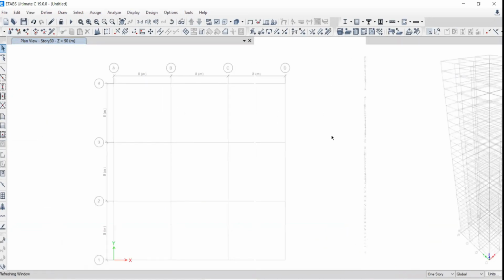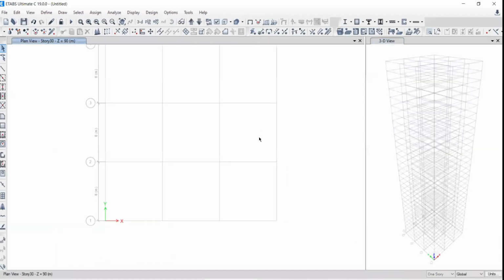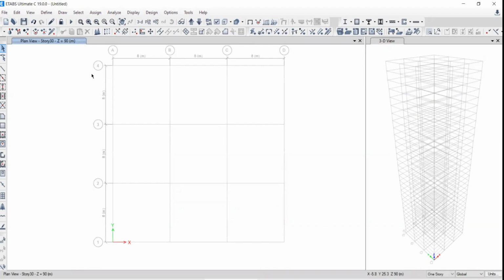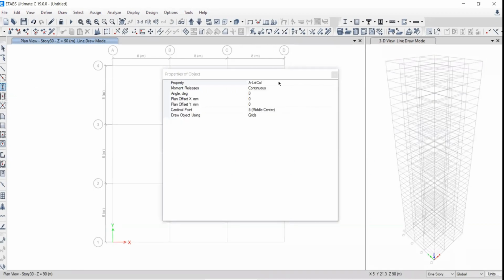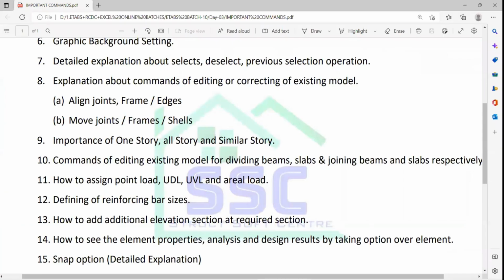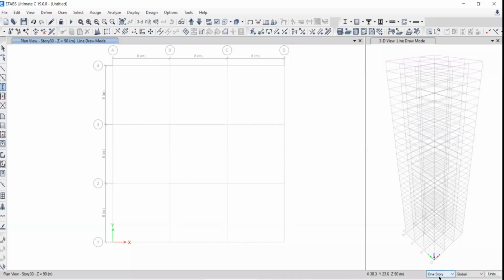How will this help you for the modeling? Now, suppose I have to draw the column at the 30th floor. So go to column, concrete column, close it. Sorry, concrete beam it is. Column, close it. With the one story option, see the option is checked as one story. Drag it from left to right. Go to this and excluded view.